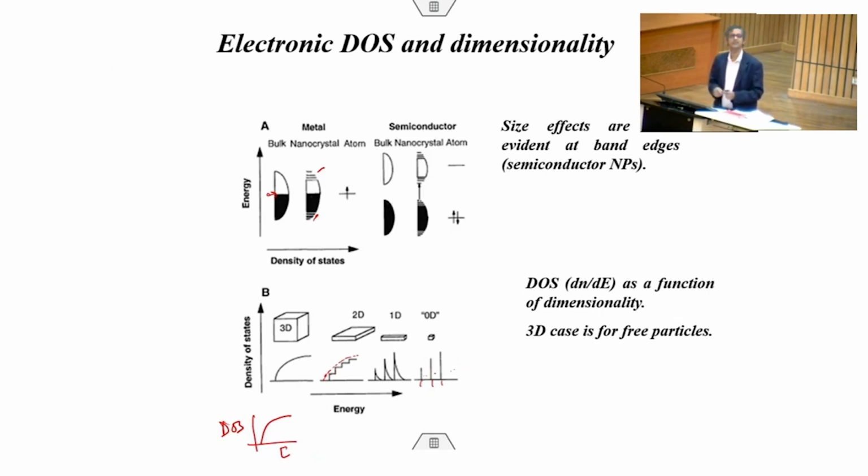It's just like electrons in a well. So if you put electrons in a well of length L, what will happen to the energy bands? That's exactly the same thing that happens in 3D, correct? Or in 1D or even 2D. In a semiconductor, between a bulk and nanocrystals, again the same thing can happen, but there is a band gap, Eg, right? Discretization can happen both in the valence band as well as in the conduction band. It can happen in both cases. Insulator, it does not matter, it does not make much sense, that is why we do not discuss it much.